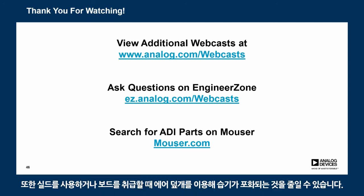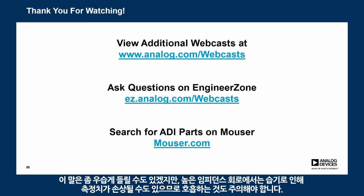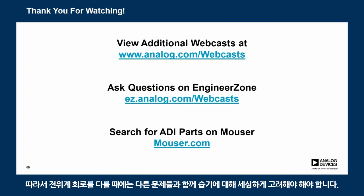You could also reduce humidity fluctuations with an air baffle, like using a shield. Even when handling the board, this is going to sound funny, but you want to be careful not to breathe on the high impedance circuit, because that's going to introduce moisture and corrupt your measurements. So yes, when you're dealing with electrometer circuits, you really have to worry about every little thing, and humidity is one of them.